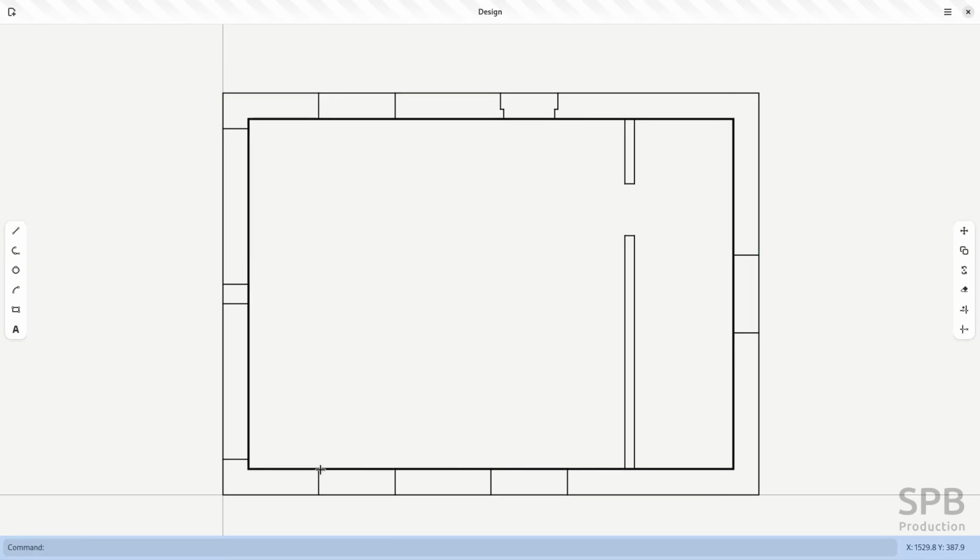So what I have to do is actually redraw these parts of the line, and then I will delete these rectangles. So I will fire up the line tool, start here, click here, hit escape, and then start line tool again, click here, and I'm basically redrawing the lines.